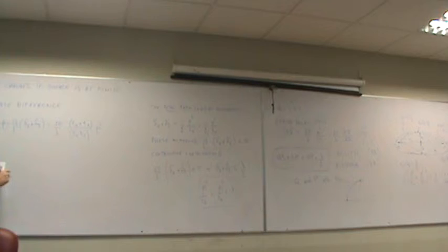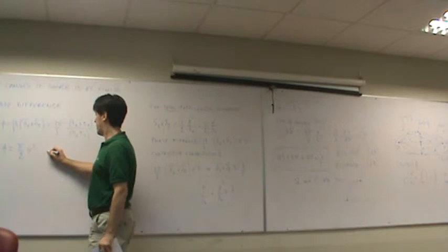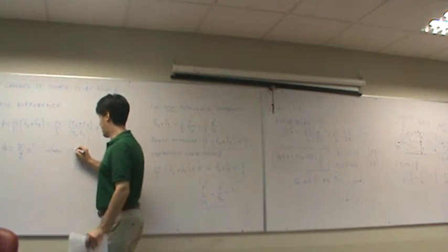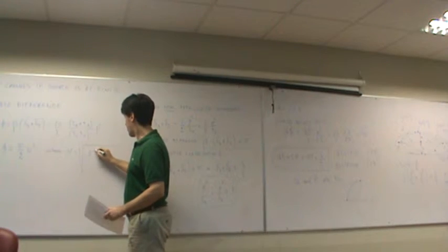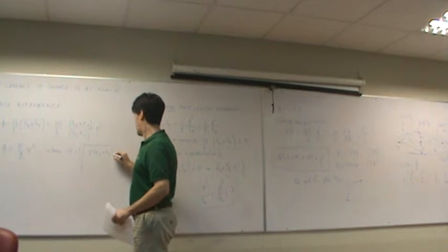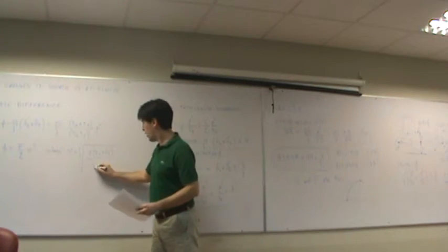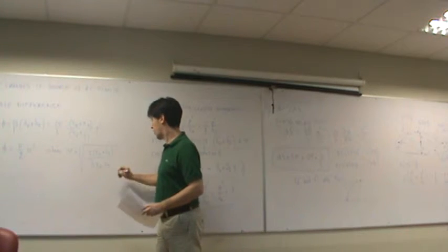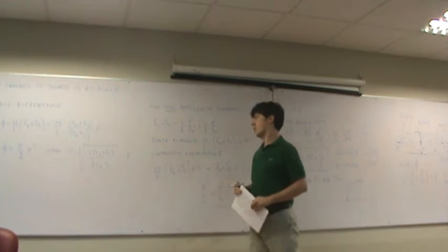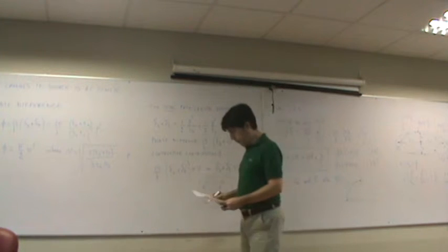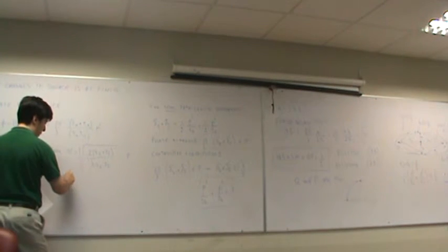This is quite often rewritten as follows. This is a typical way that we rewrite it, where this parameter v has got this expression. We will use this parameter in planning of radio systems. This is called the Fresnel-Kirchhoff diffraction parameter.